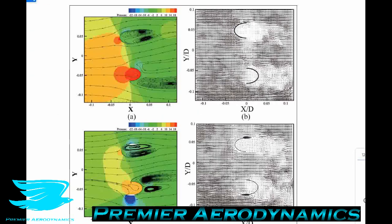If we compare these two blades, we can see that the flow inside the drag only producing blade is a little bit slower than the other one, and that indicates that we probably are getting a higher total pressure and a higher static pressure in this because the kinetic energy from the flow is being dumped into the blade, and that results in the dynamic pressure being converted into the static pressure that we feel. So that's, I think, what's happening here.